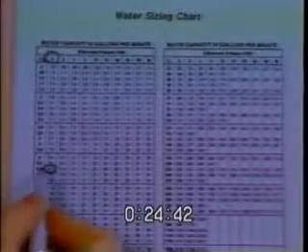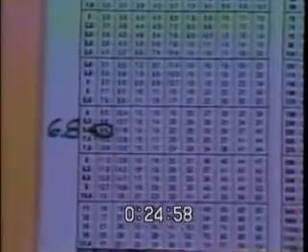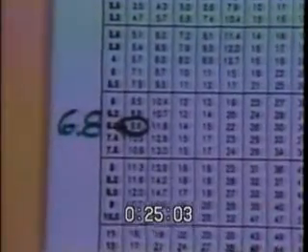Now taking that and going down the 2 column, we go down until we hit our gallons per minute, or as close to it as we can get. In this case, 9.6 as close to the 10 gallons per minute as we can get. Moving then to the left, you'll see that the CV is written right there. In this example, it is 6.8. This method is very quick also, but not all the pressure drops that I need are shown. This chart is available in the green catalog.